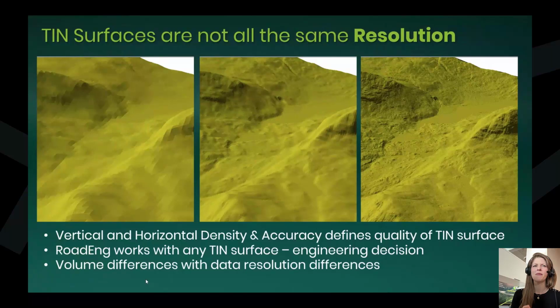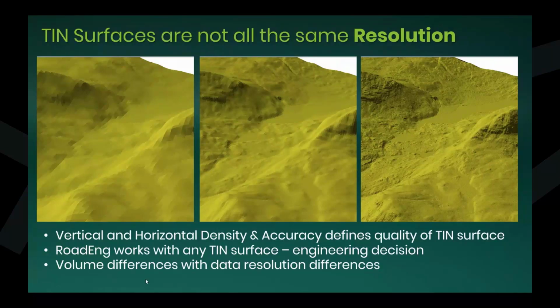We ran a little bit short of time, but Matt, do you have anything else to add on this topic? Not much. Not all survey data or surface information is created equal. And as Aaron said, the density of the data is important. Aside from just the density, though, just because you have lots of points or lots of lines doesn't mean that it's good data as well. So your accuracy is going to play into it. Conventional survey data is obviously pretty dependent on where the surveyor puts the rod and decides to measure a point.